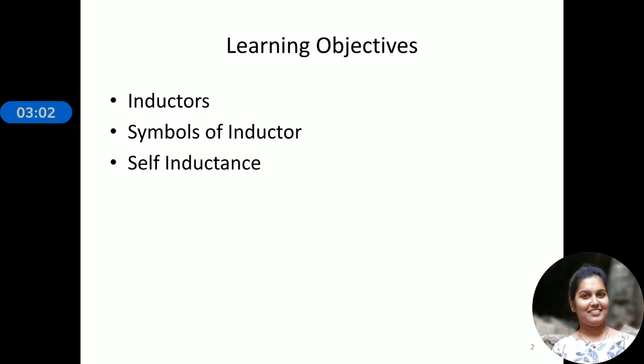So there is another important property relating to a wound coil that also exists, which is that a secondary voltage is induced into the same coil by the movement of the magnetic flux as it opposes or resists any change in the electric current flowing in it.